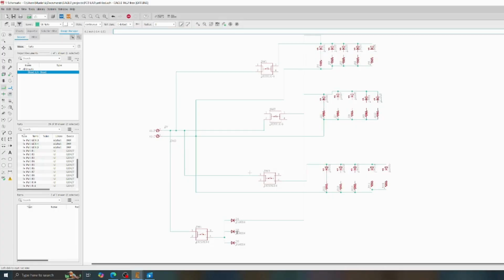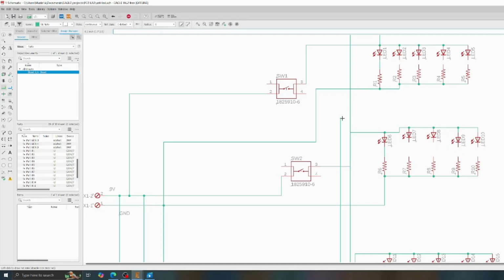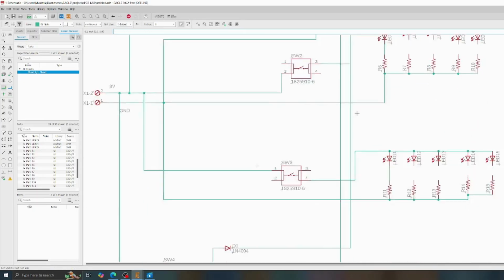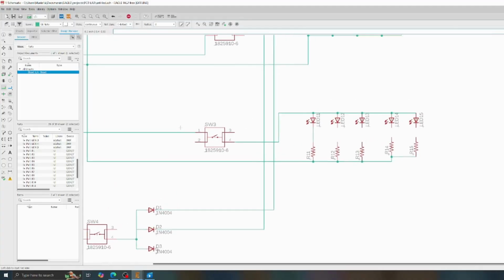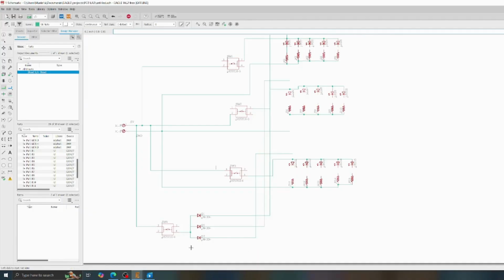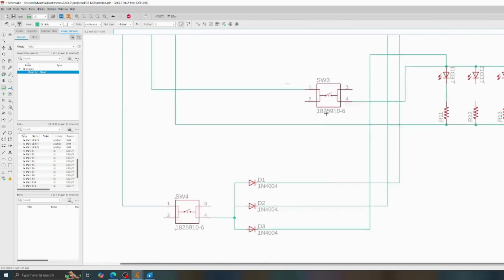And we're going to do the same thing for the other ones. We're going to drag here, stop right there, go right above the first LED, and connect to the anode, or the cathode, I'm sorry. I get those mixed up a while. Last one with the third one, we're going to come right here, click right there, go right above the cathode, and connect it. So now our button is completely connected. So now this should work exactly like our Tinkercad model.